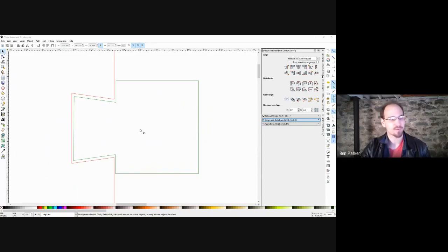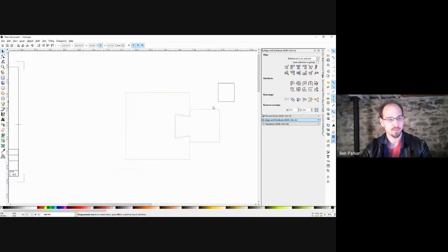As long as this is bounded, the laser is going to go back and forth like this, and it'll cut very quickly and just kind of remove the top layer as an engraving. But you can set all those in the laser program. But for design purposes, I like to keep my color coordination because it keeps everything organized.